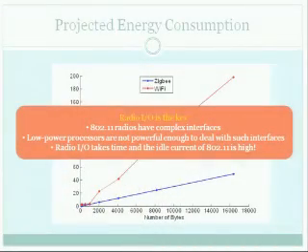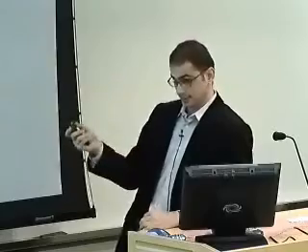Yes? Do you take into account collisions and the power consumption required when you need to respond to a collision? Correct. So far, I'm not talking about the network. There is no network. There is only a single sensor node trying to transmit a packet. The reason I did that in this case is because I want to demonstrate the inefficiency in the processor radio interface. What is coming up is also a quantification of what you just said: the effect of the back-off mechanisms and the fact that you have to retransmit a packet in the case of network congestion. There is a significant part there that is coming up right away.